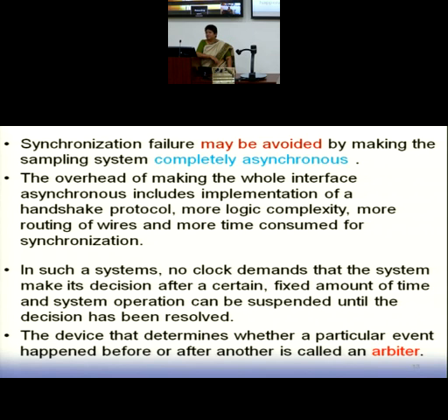If we are not sure the data is fully resolved, we will not allow it to pass through, so that we do not want my system to go into a failure state. So here we have to take a decision. My two inputs will be the clock and the asynchronous input, or input coming from another clock domain, whereas in the case of bus arbitration logic, it is usually two requests coming for bus access at the same time. It's more or less the same thing.